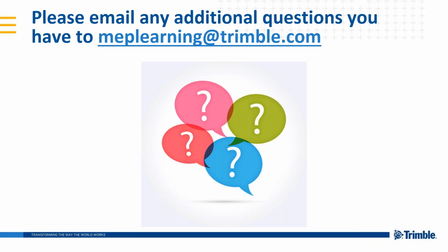When I save my jobs, do all the marked up drawings get saved with it? Oh, absolutely. You save your job. There's a selection for digital takeoff when you go to save your job. It's an estimate and digital takeoff. Make sure that checkbox is checked; it defaults to checked off if you have digital takeoff in it. But yes, and then when you load it up later, all your drawings as well as all your notes, legends, and annotations are visible as well.